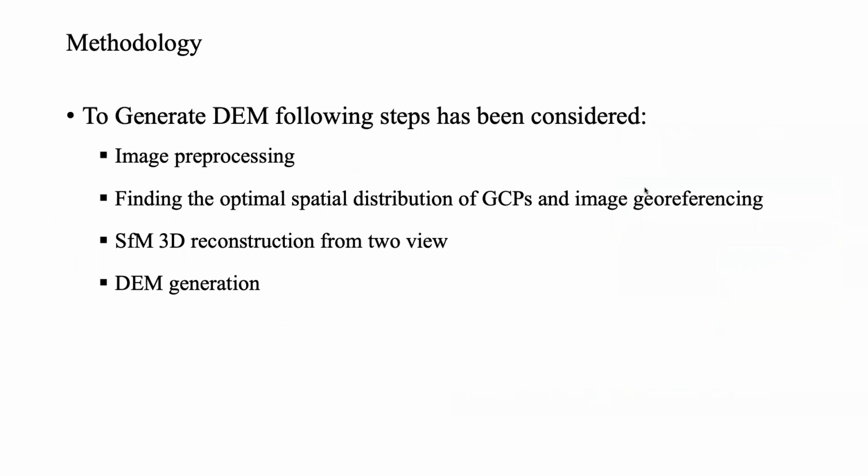In terms of methodology, for generating the digital elevation model, I follow these steps. First of all, image pre-processing, including cropping the horizon for all the images. The next step is finding the optimal spatial distribution of GCPs and image georeferencing, and then SFM 3D reconstruction from two views, and the last step, digital elevation model generation.